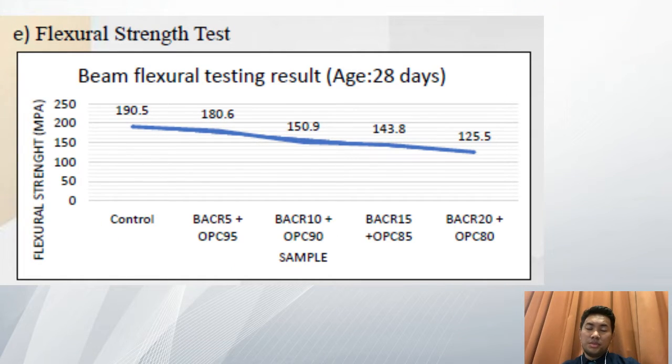As shown in figure 3.5 for the flexural strength test result, it behaved similarly to the graph plot when it displays a linear form. Essentially, this study will determine the ideal quantity of bamboo ash to utilize in order to achieve a load almost comparable to that of the standard concrete. While this data is not exact, it demonstrates the relevance of bamboo ash utilized as a replacement for cement. The graph depicts a decreasing plot. Nevertheless, BACR5 is the closest since it has the least difference and is comparable to the control sample performance.